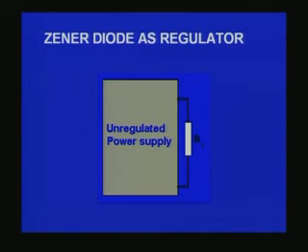So the load here is any appliance which requires electrical energy. When I change the load, or if the current being drawn by the appliance is different, which can happen all the time, then you would find the voltage actually applied across the load will no more be a constant unless it is a regulated power supply.